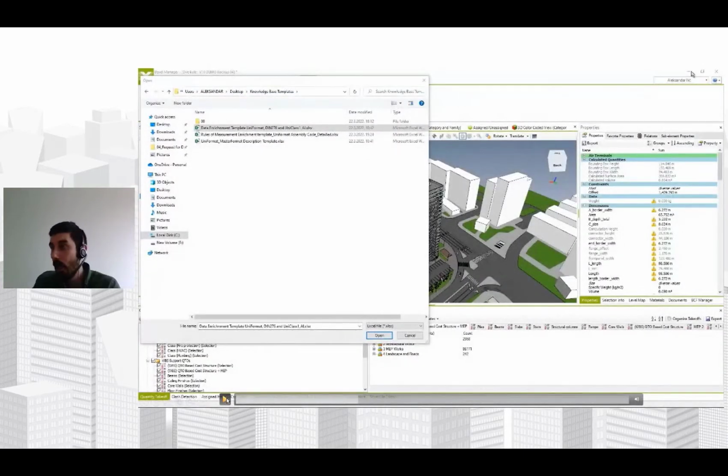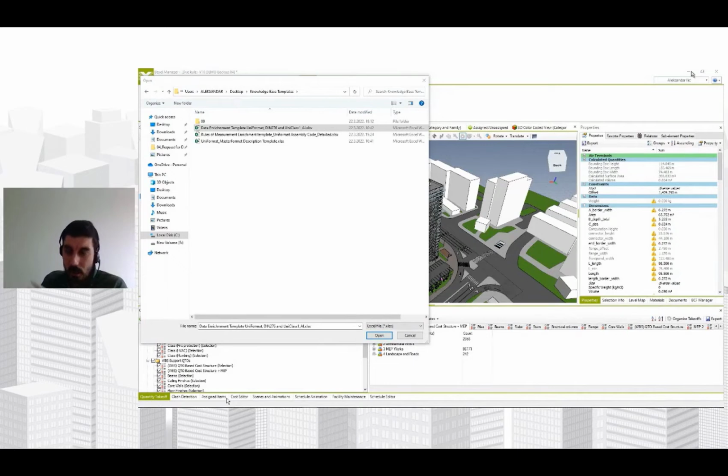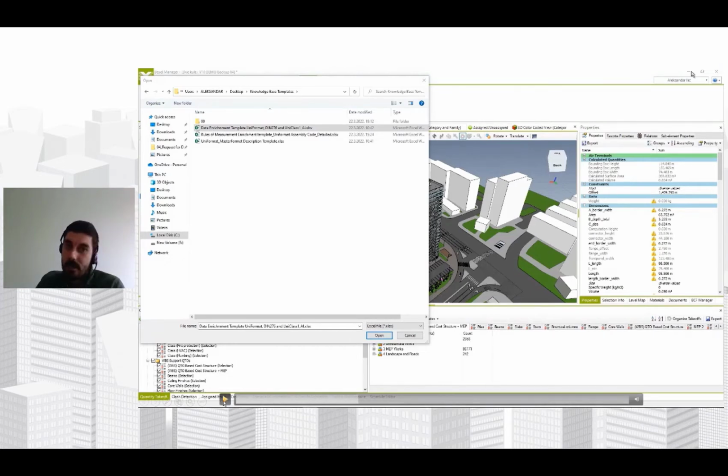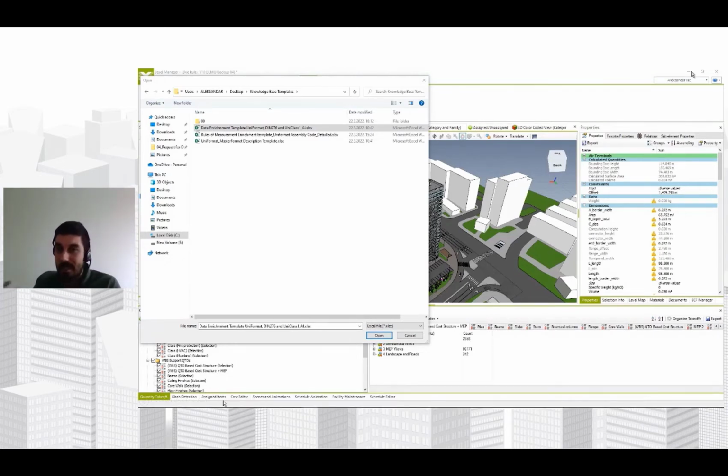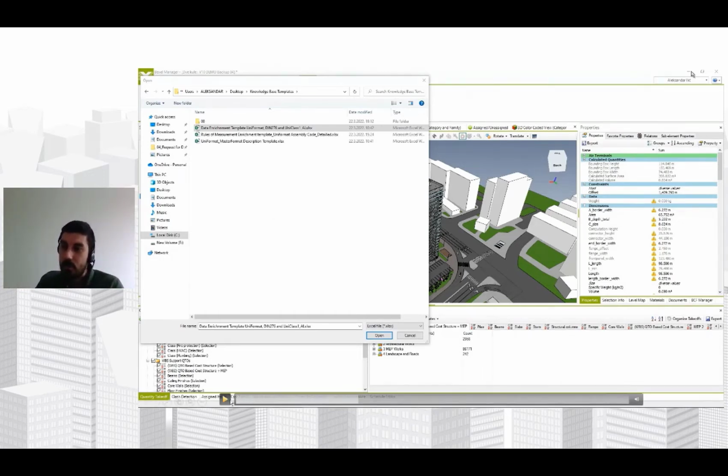Of course, it's probably not going to be 100% accurate. It's not going to cover all possible scenarios, but from our experience, more than 90% of the elements could be pretty well classified just relying on this information. You just need to, in your process of developing the model, follow certain rules and say, okay, when you are defining the element wall, build it from the category wall and not use some other specific category, and specify system names in the MEP and things like that, things that are more or less standard across the world when it comes to the development of BIM models.